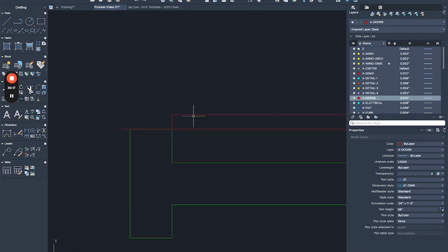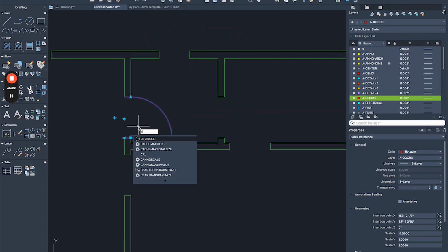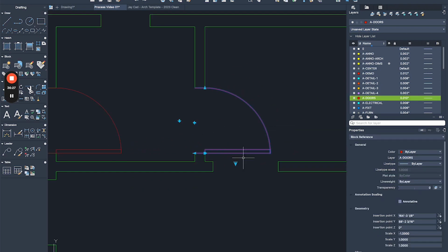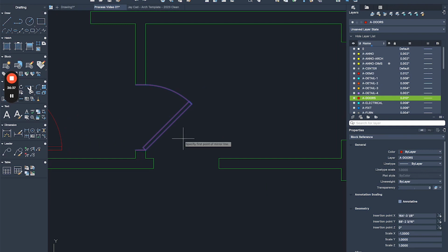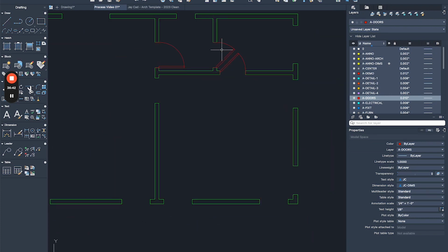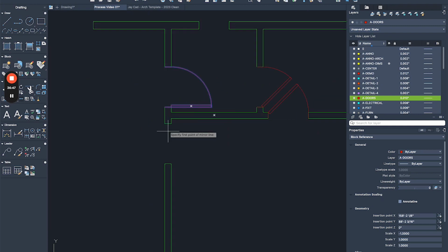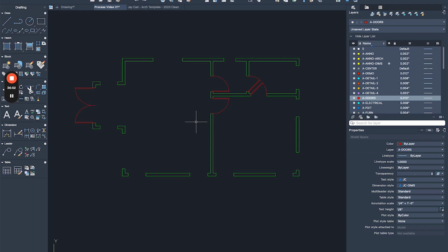You see that this one is wider than the wall, so you can actually modify it from here too. A lot of controls, one of the nicest blocks ever made. It's actually made by Autodesk. It comes with your software, so really handy. Okay, so I'm gonna hit the open 45 degrees. You can also switch the swing portion of it. So I did 45, so that way these two doors don't hit each other when they're represented visually. Then one more door is this one, which is from the laundry to the bedroom, and this is looking good.